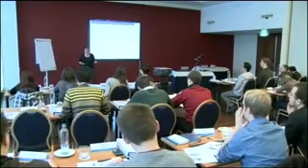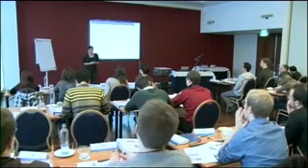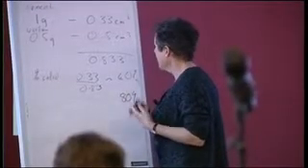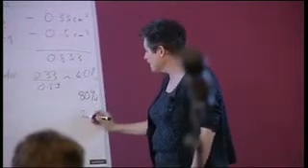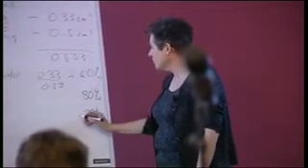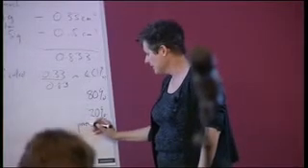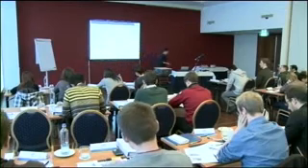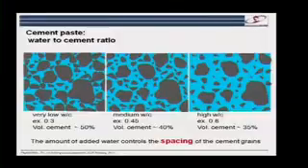Come on, that's easy. 2 times 40% is what? 80%. So what that says is that, very roughly speaking, for a typical concrete, I have about 80% solid, and about 20% of the volume is pores. And a volume of porosity up to about 20% is typical for a material that will give you good mechanical performance. But this is basically what it's all about. It's all about filling up space and reducing the amount of pores.